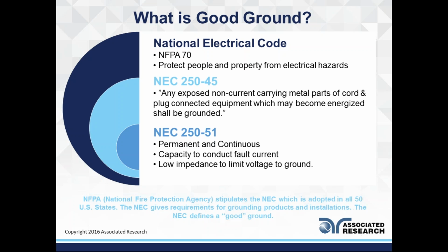It's not there for a functional use. We won't be purposely passing any current through that path. And plug-connected equipment which may become energized shall be grounded. So pretty much if there is an area of your product that may carry fault current, we want to make sure it's grounded so that current finds a path back to ground.